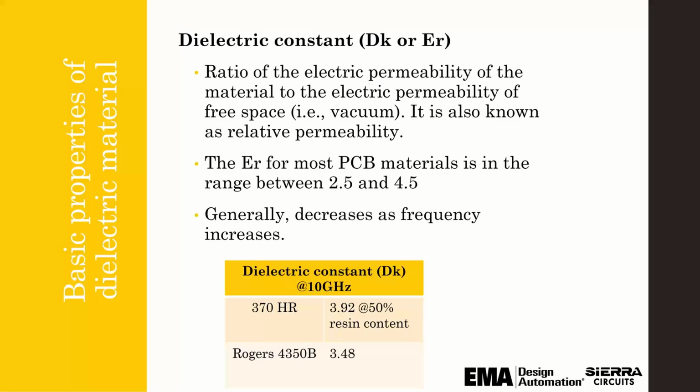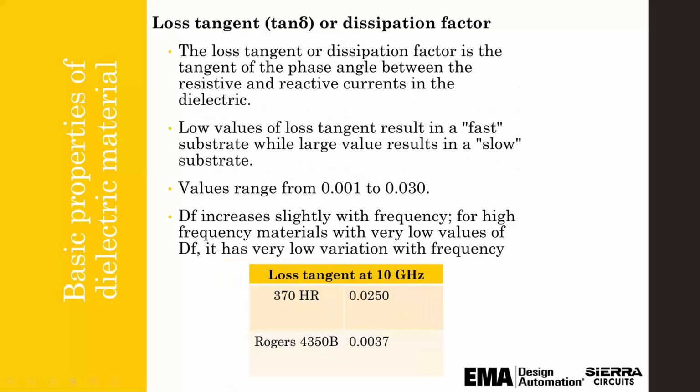And actual resin percentage in a core prepreg really varies based on composition, and it changes after lamination when you have a press out thickness, and that press out thickness is based on your copper percentage. So there's a lot of things that vary the Er and the Dk, so it's really critical for your manufacturer to help you calculate that for your specific stack up.